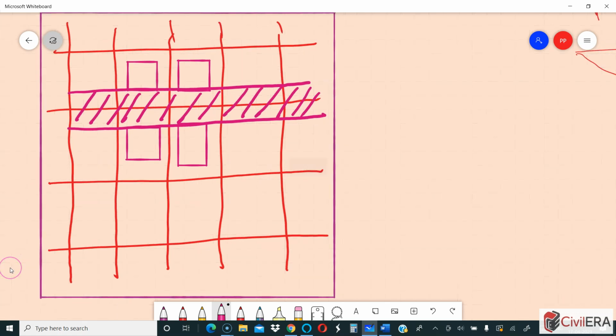So you will see a band in both directions. So this is the basic principle. So you don't need your concrete in the tension zone. So in the bottom region you are removing as much concrete as possible by doing this. So this can be a cover, and this can be a cover required so that you ensure your rebars are protected from moisture and other corrosive agents.